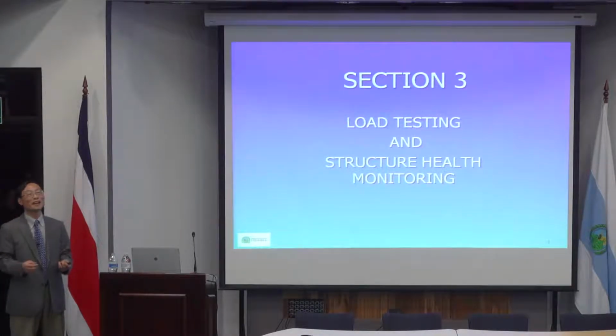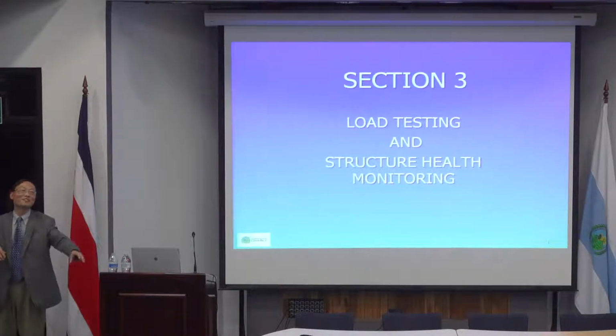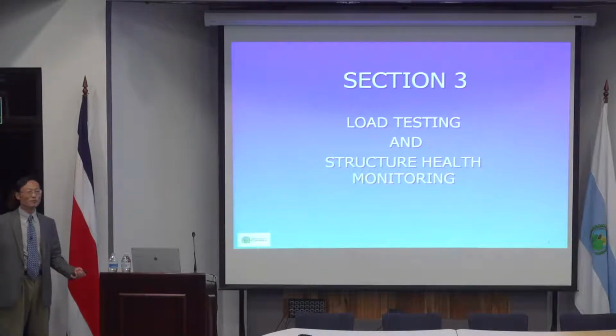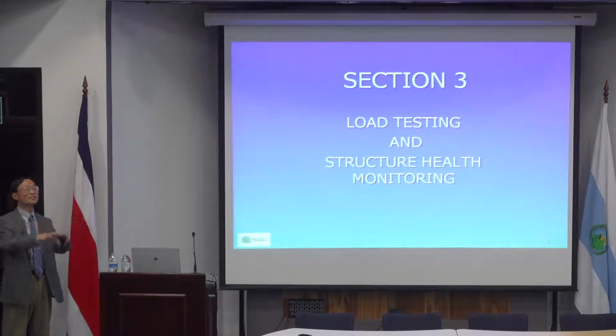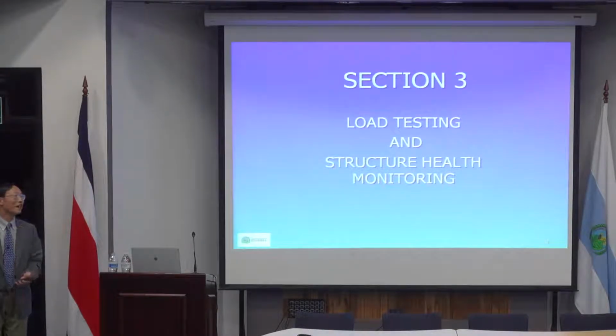We all know that if you have a very, very short bridge and you have many, many girders, when the truck comes, these girders have very much no impact at all. But if you have a very, very long bridge, when the truck comes, most of the girders will have similar deflection. They will share loads very uniformly. And that's why in the new AASHTO, there are mathematical equations to calculate how live load will be distributed into each girder depending on the characters of the deck, geometry, and so on.